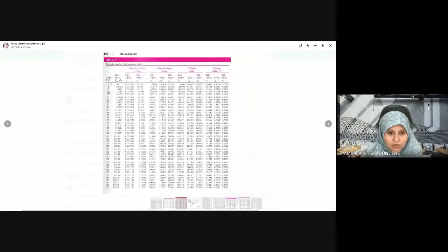So for 15 degrees Celsius, 62.982, and 25 degrees Celsius outlet of the water is 104.83. We choose the hf, the liquid enthalpy. So that is for water.